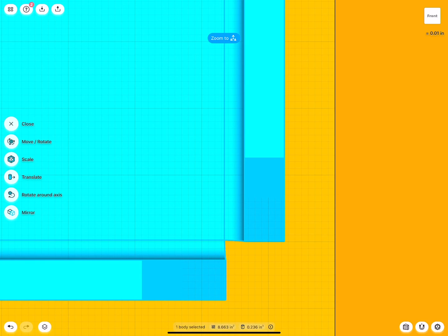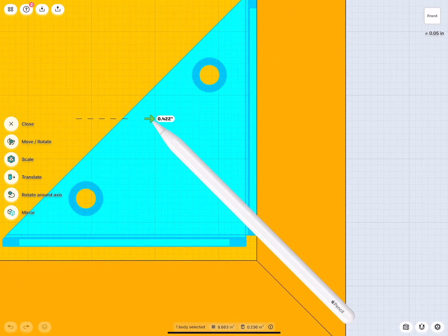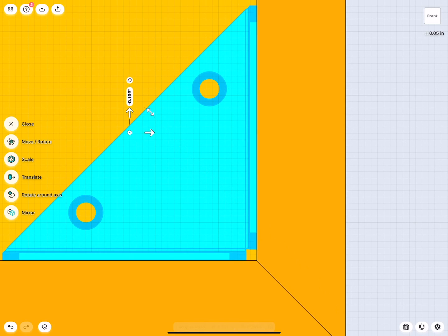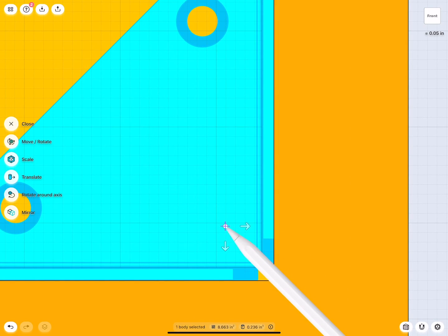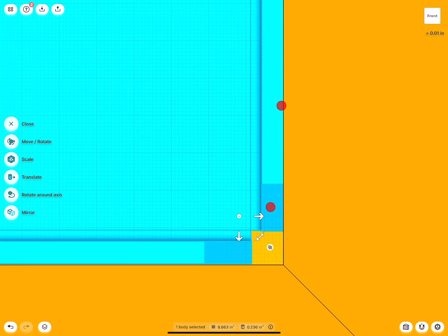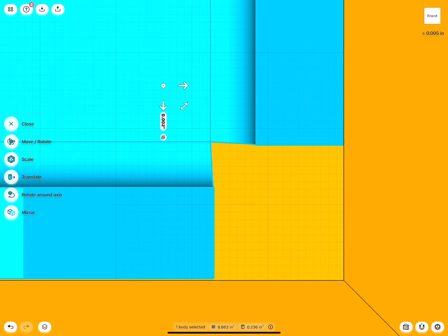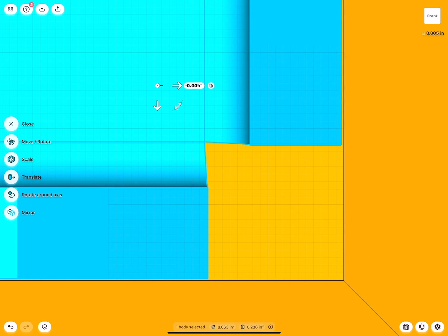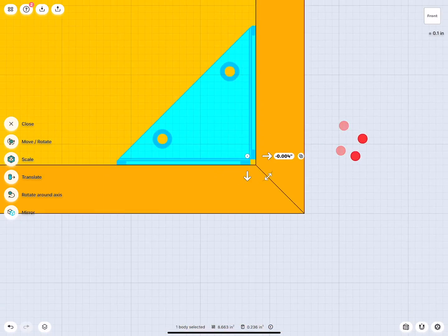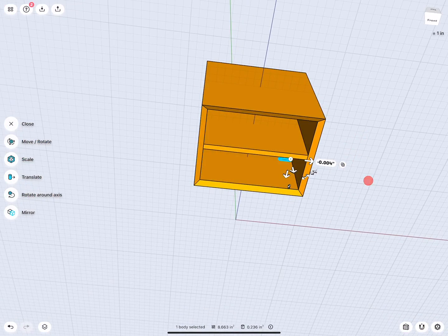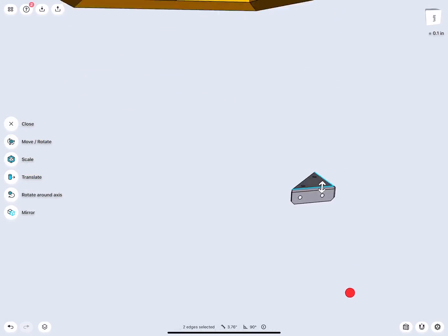Now keep in mind, everything in CAD is super cut, super precise. In reality, surfaces aren't as that straight. So if we want, since we're working in furniture, we could just try to very carefully position this. I move this widget a little bit closer so I can zoom in more and just fine tune this position. So that, for example, is pretty close. But if you want to be very precise, let's say it's also a mechanical part, that we don't have the luxury of being a little bit more loose, I will show you this approach.